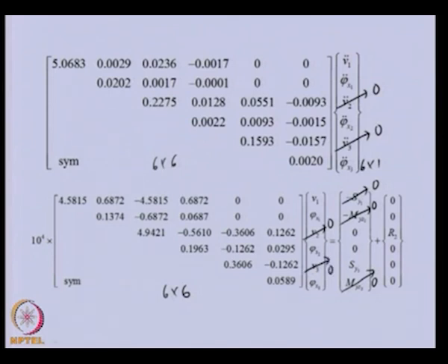So once we apply these boundary conditions, we need to look into the right hand side. In the right hand side, those terms in which we have zeros only, we will be picking those equations. First equation, second equation, then the third has one unknown, so we will eliminate this particular equation from the reduced form.